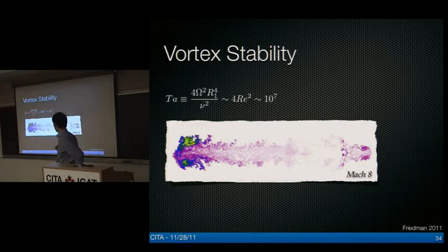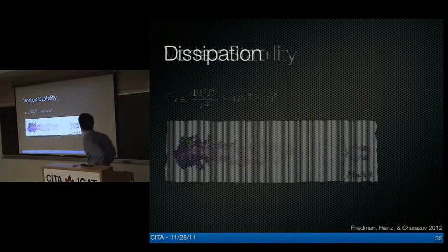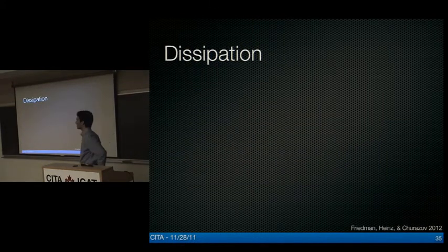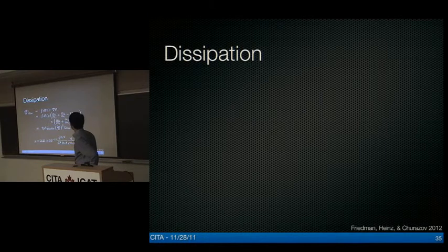And once it looks like this, it dissipates numerically very quickly. Right? Numerical viscosity will quickly dissipate this vorticity over here. Which is why, as I showed you before, for high Mach numbers, the efficiency peaks and then drops very quickly because of this dissipation. Okay, so speaking of dissipation, even if there is no turbulent dissipation, even if the vortex rings are stable enough, you can still dissipate the energy viscously, just like you do in accretion disks, whatever your source of viscosity is. And so you can write down what the viscous dissipation rate is.